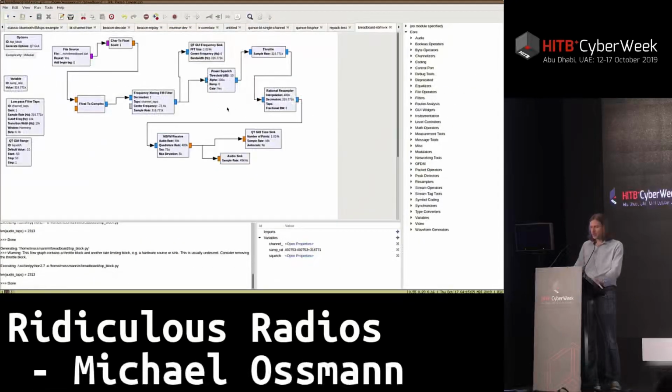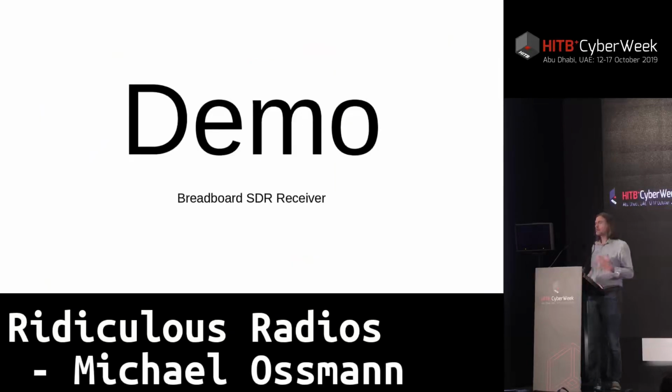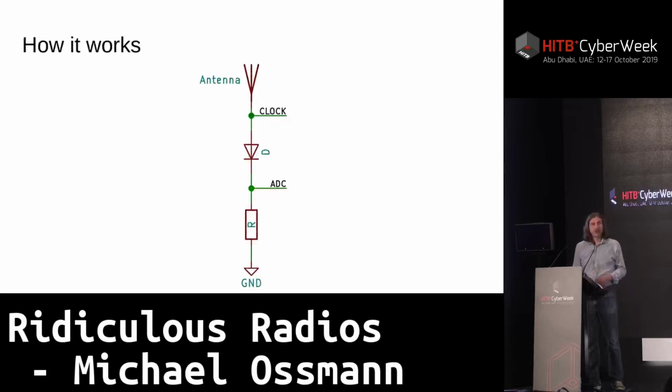Now, one drawback of this approach is that I had to use a fairly high-powered transmitter. And the reason is because there's no amplifier in this receive circuit. It's the crudest possible circuit I've been able to devise, the fewest components. And that means it has some drawbacks, but it is functional. As long as the radio signal is strong enough, this simple circuit that can be built out of components that you might find in any electronic device